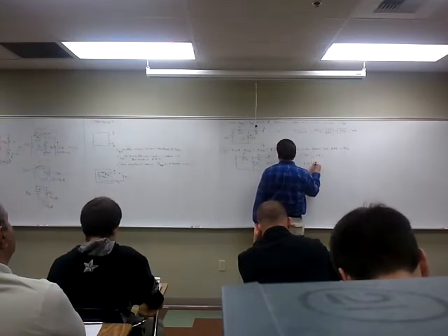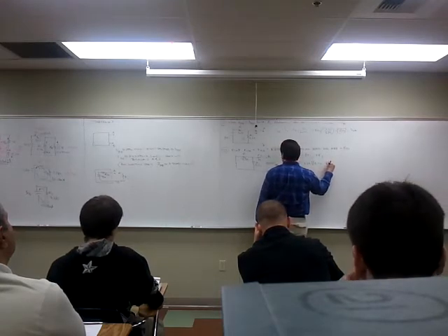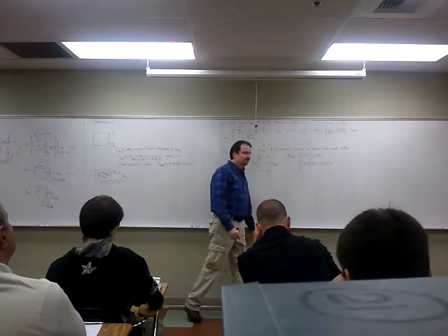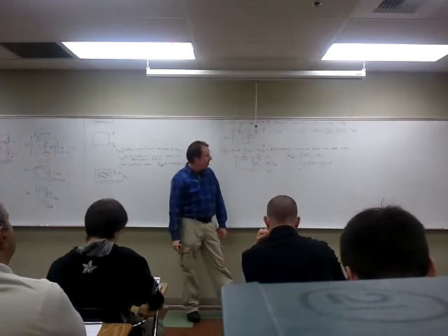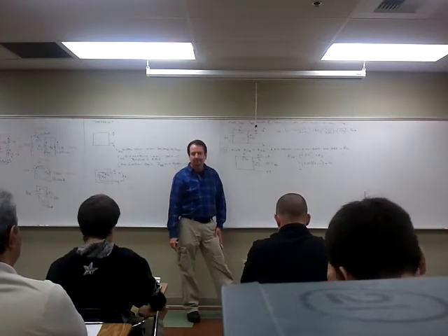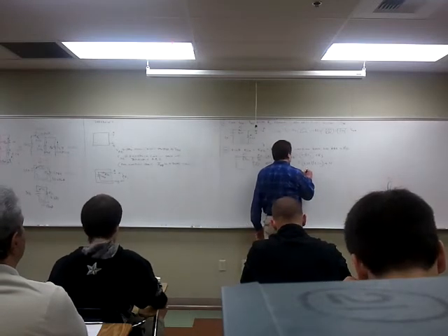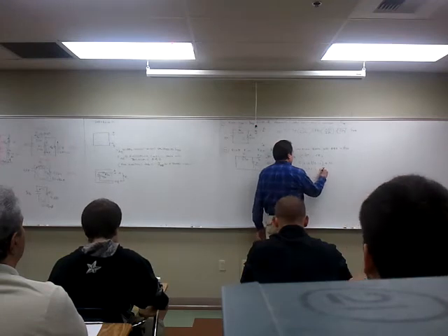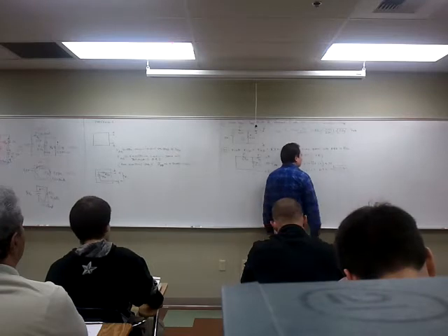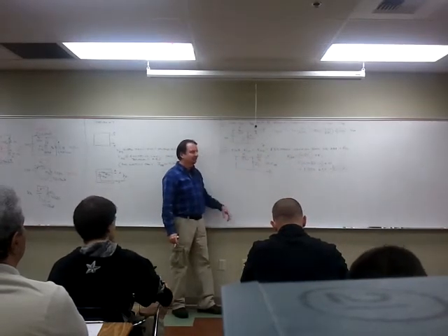So that would be equal to 3.3K in parallel with 2.2K plus the 1K. So what's 3.3 in parallel with 2.2? Around 1.6, something like that. What is it? 1.32K? Oh, that's a lot. Plus 1K is 2.32K. That's the resistance. If you put an ohm meter here, isn't that the total resistance looking back in?